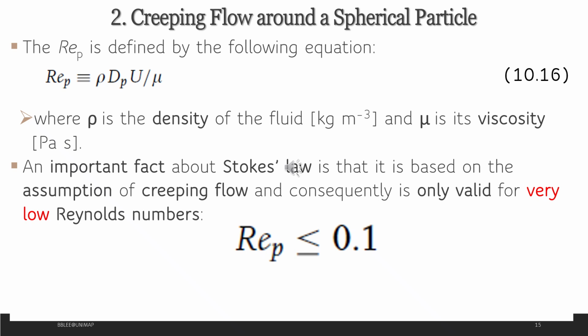Now this is important. The equation 10.15, the drag force, is only applicable when the creeping flow meets the requirement of low Reynolds number, less than 0.1. The Reynolds number must be less than 0.1. Only then can you use equation 10.15 to calculate the drag coefficient.